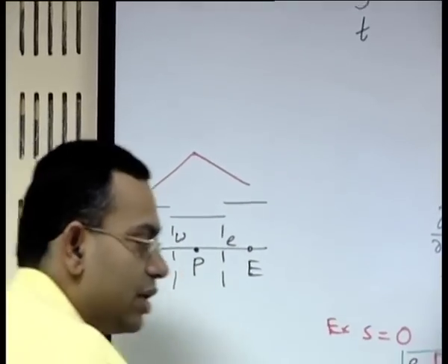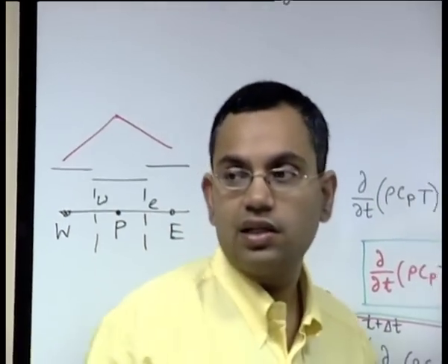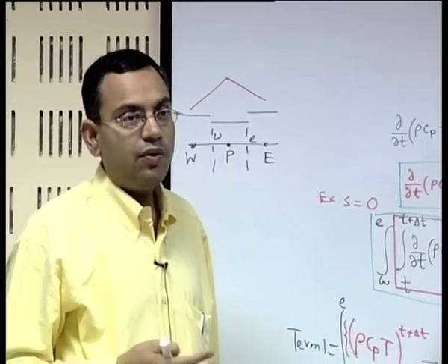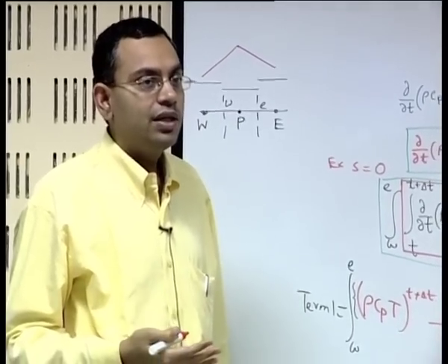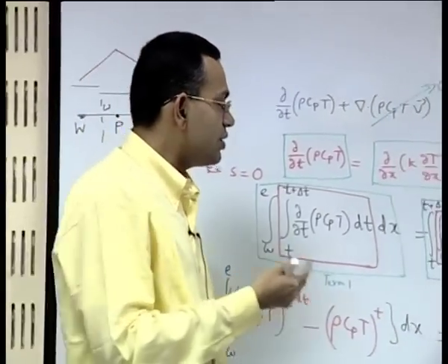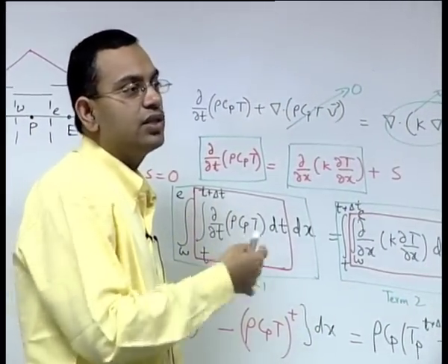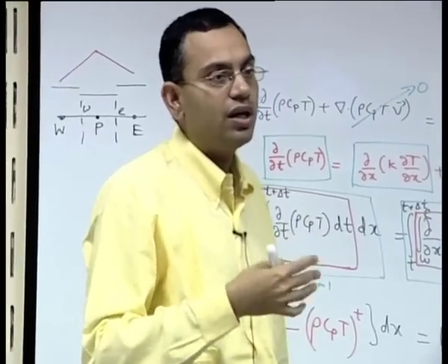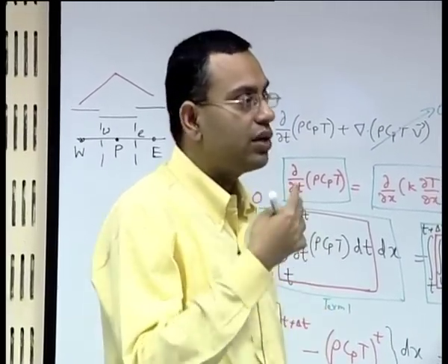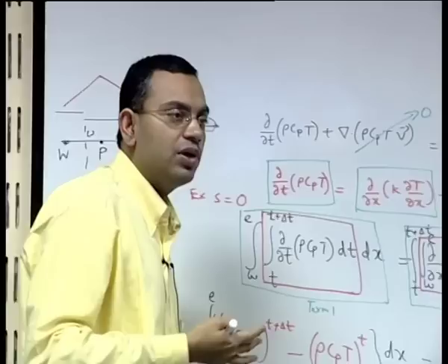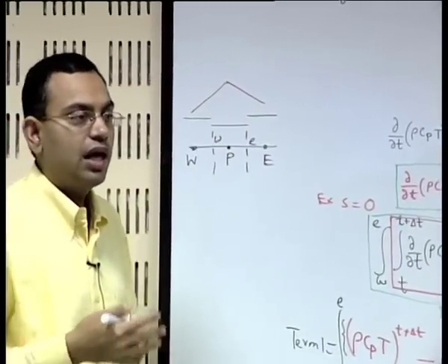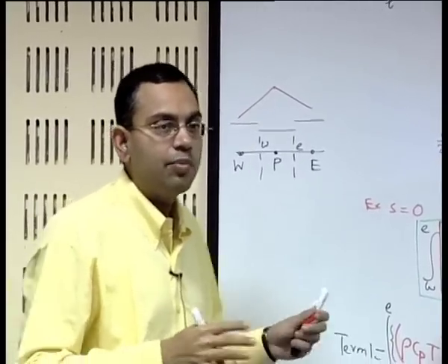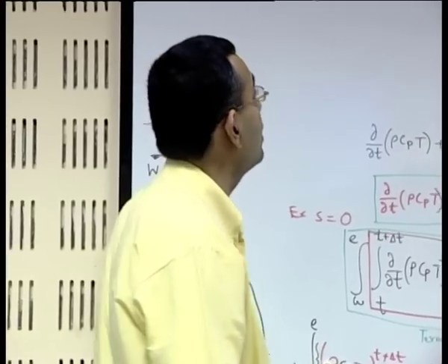So we can see that for different terms we can easily take different types of profile assumptions. We have earlier discussed that why we can do it, because at the end this history of profile assumption is lost once you evaluate the integrals. So the profile assumption is solely for evaluation of the integrals, you do not require this for any further interpolation or any other calculation, and therefore you have the flexibility of using different profile assumptions for different terms in the governing equation.